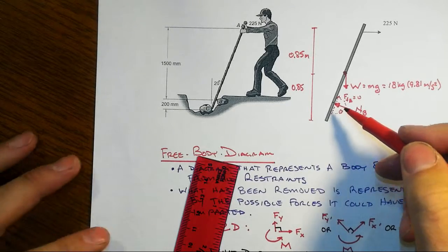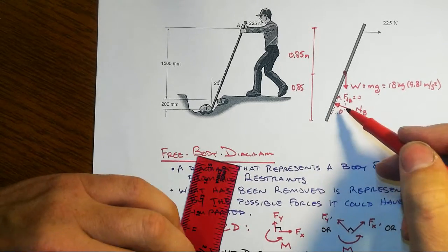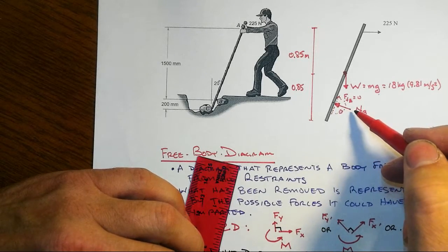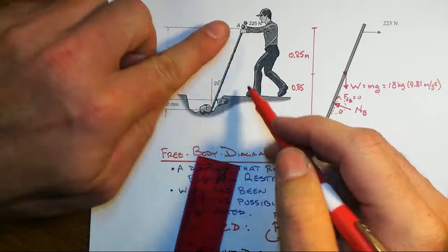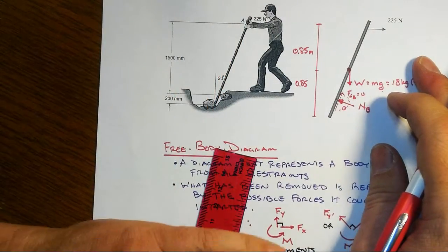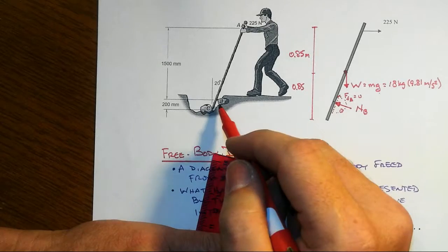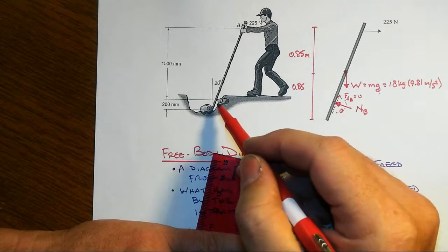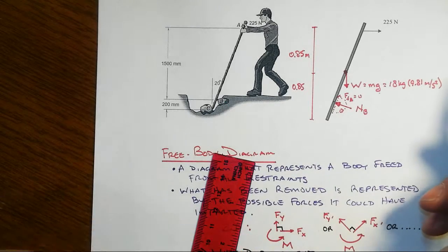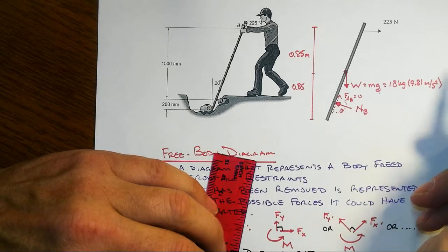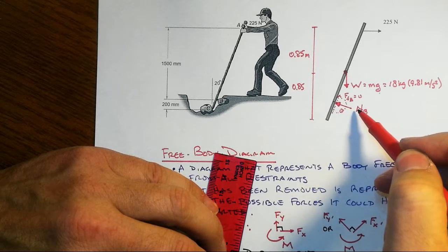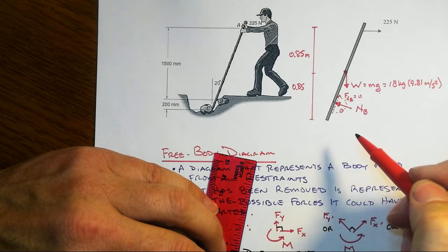This is a lot like a roller on an inclined plane, same kind of thing. Now there's probably not a hold down force like a roller would provide, because I could take this prybar and rotate it out this way, and there would be no restraint offered by B, unless somehow I bonded the prybar to the rock with epoxy. I don't know why I would ever do that. Probably wouldn't. So we have one and only one force pushing back on the prybar at B.